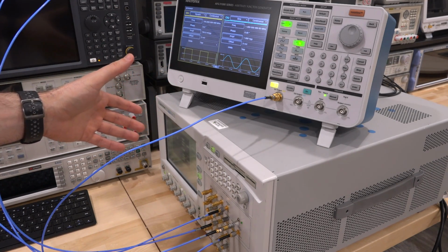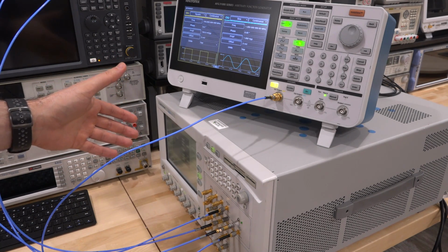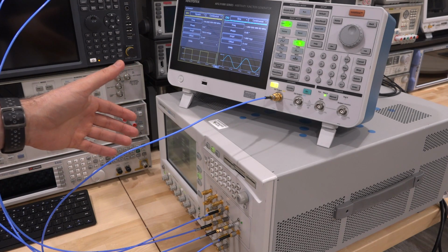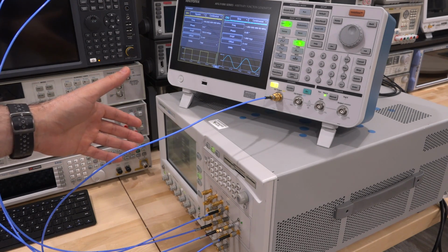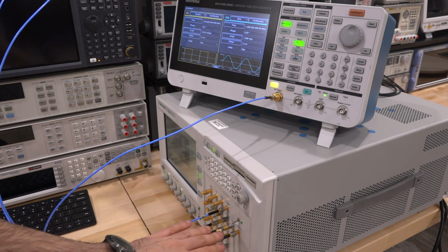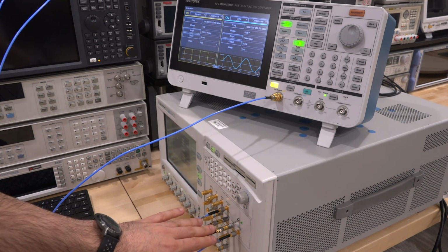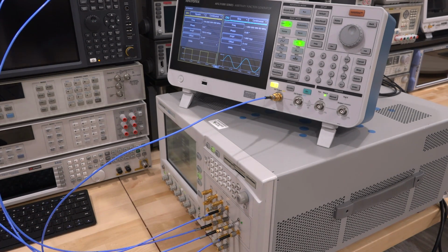So that means the eye is going to move back and forth at the rate of 100 megahertz and with fixed amplitude. So it's going to jump between two separate positions. So it's going to have the highest histogram distribution presence at the extreme edges of those 2 points. Now this thing can do up to a gigahertz of jitter frequency, and it can do it up to plus or minus 200 picoseconds. So it's quite a lot, and we should be able to easily see that even at low data rates, even less than a gigabit per second.